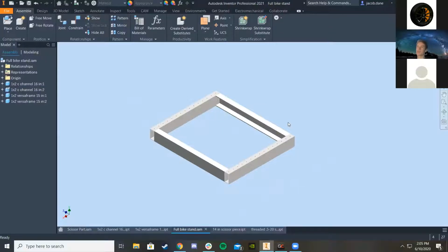But also in Autodesk, depending on how much experience you have, if you have a good understanding of the faces that you're going to have to constrain, it doesn't exactly matter how it's aligned before, because when you constrain everything, Autodesk will automatically put everything together the way you want. That makes sense. Okay, I'll just get better then.